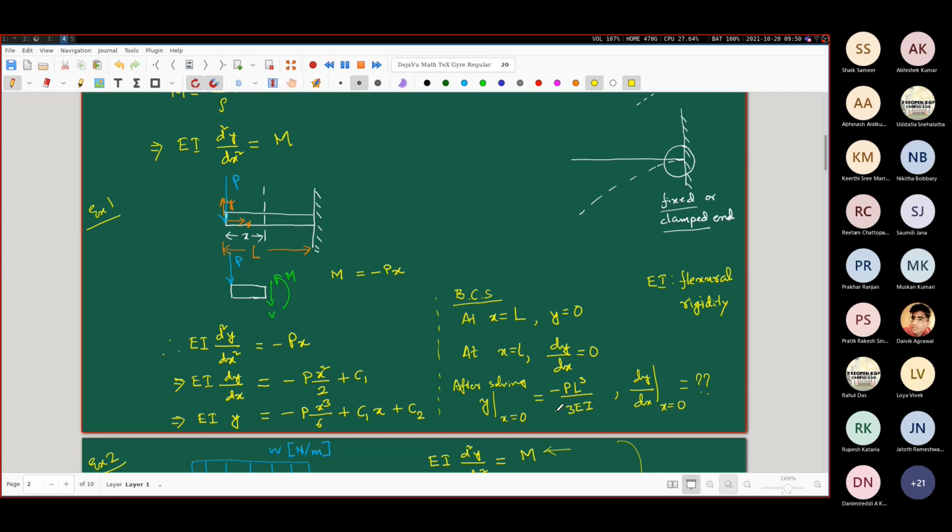Similarly, for the case of d/dx of x to the power n, without thinking now you can write those results down. Similarly, when you encounter these kinds of elementary situations, these fundamental elementary situations, you should be able to immediately recall in your mind that the deflection at this end where the tip loading is being applied is going to have a magnitude of PL cube by 3EI. The minus sign is only indicating that the deflection is taking place in the downward direction.